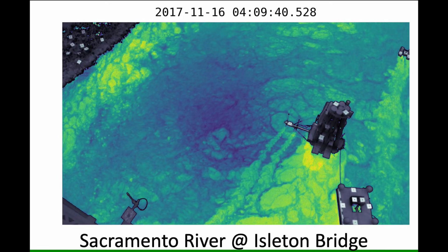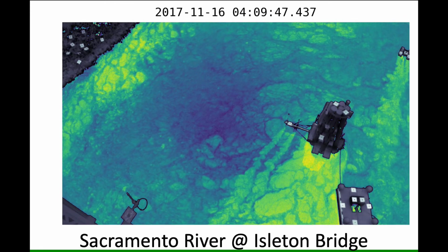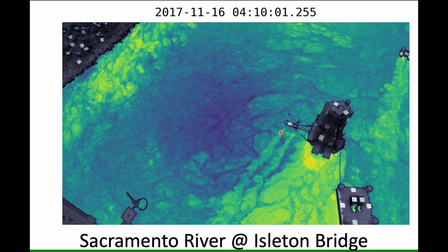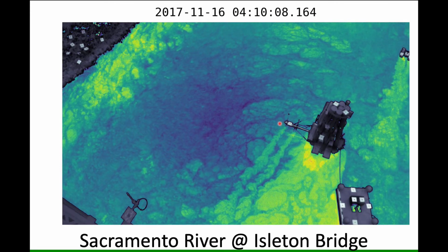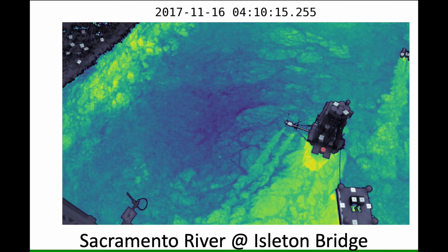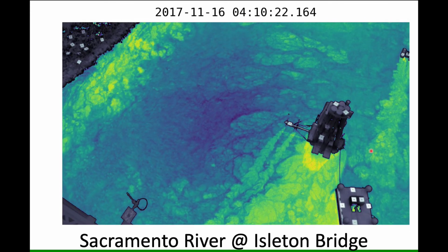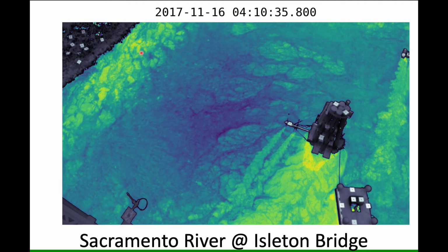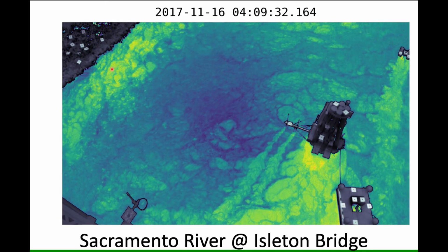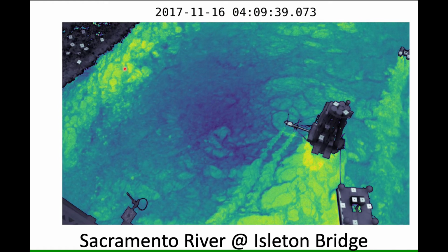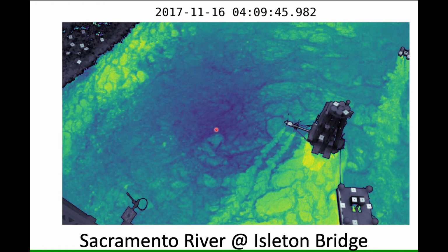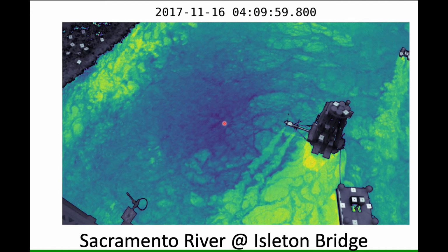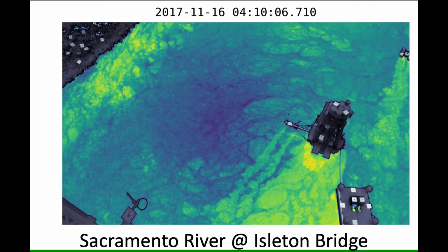This is a tidally driven flow. Here we're at a modest Reynolds number, and we'll see that we certainly have a strong Kármán vortex street, as I mentioned, coming off these two acoustic instruments. We see a vortex street coming off the piling cluster, a vortex street coming off this anchored pontoon boat. We see eddies coming off the bed in the shallow bank of the river region, but we see in the deeper channel a more nuanced pattern because we haven't quite seen in some regions eddies reaching the free surface, although we do see a new set of eddies arriving now in time.